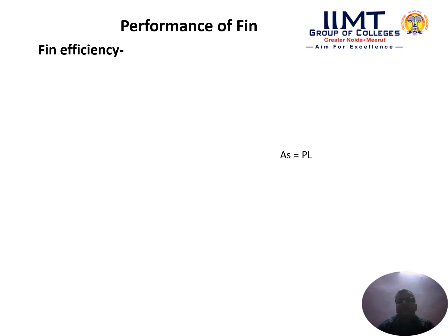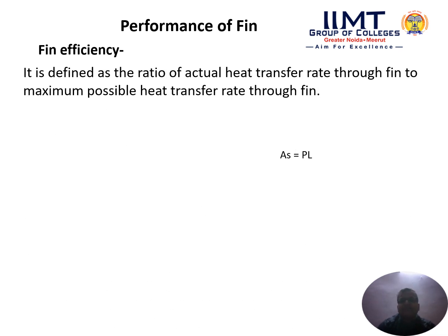What is fin efficiency? Fin efficiency is defined as the ratio of actual heat transfer rate through the fin to the maximum possible heat transfer rate through the fin. That means fin efficiency η equals Q fin divided by Q maximum.